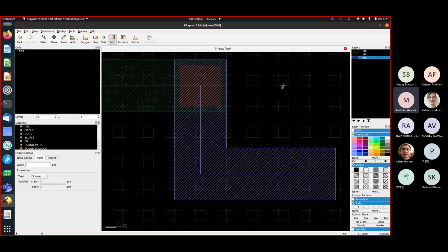But since you have so many vias on a huge layout, you try to reduce the risk of such a fail, because that would eventually lead to an open, so a missing connection, and make your chip fail. And in order to reduce the risk, you place a double via, at least in places where it's critical or where you know that there's a certain manufacturing risk. So then this would look like,